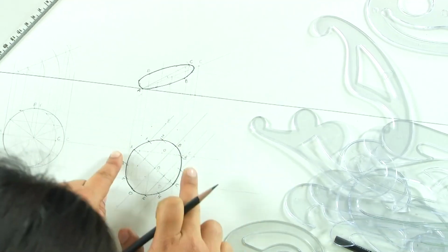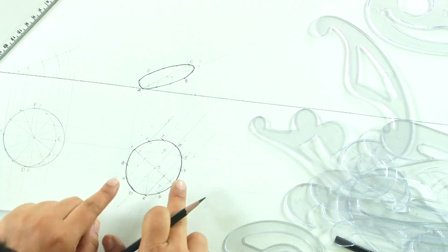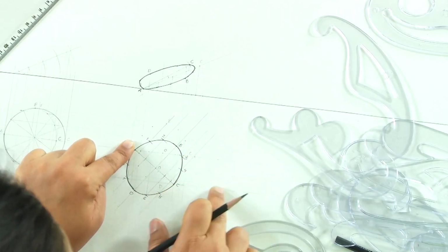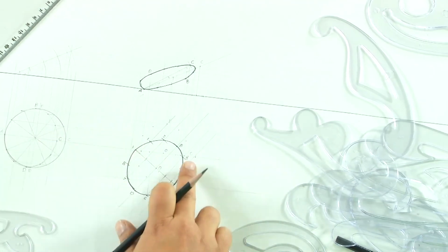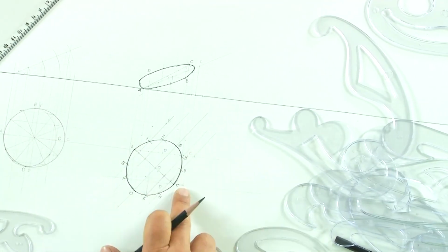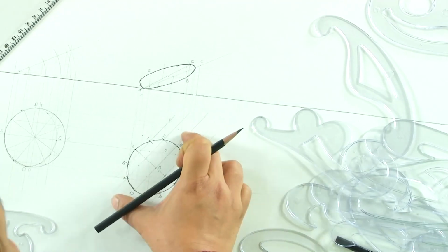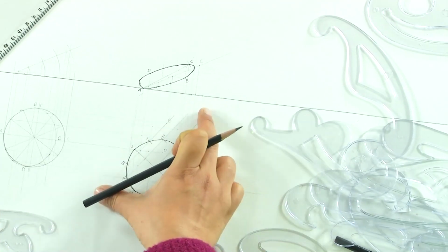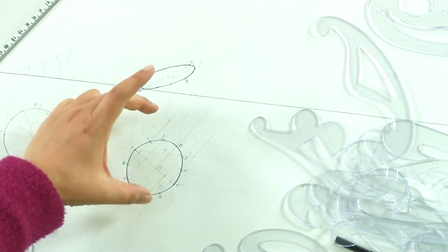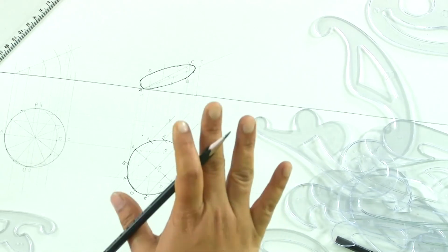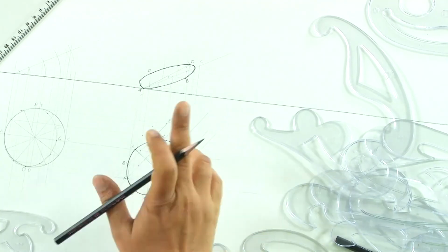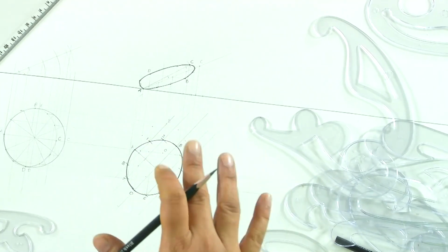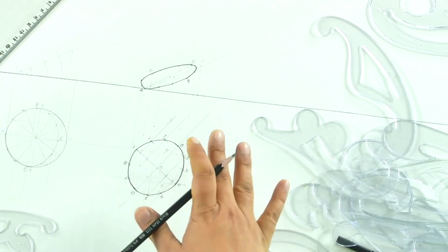So, if we were to start from the previous point, instead of inclining this AC and taking it on this locus, this straight line which is on the locus of this line AC inclined at 30 degrees, we will just incline this BD by 60 degrees, and in that case the BD and AC would still make a right angle, because BD still remains parallel to the HP, and we will be seeing the true shape and true angle of BD in HP. So, that is the step that we are going to follow.